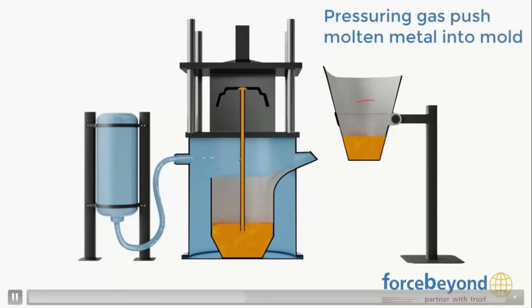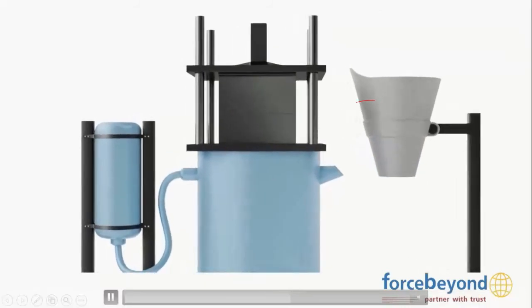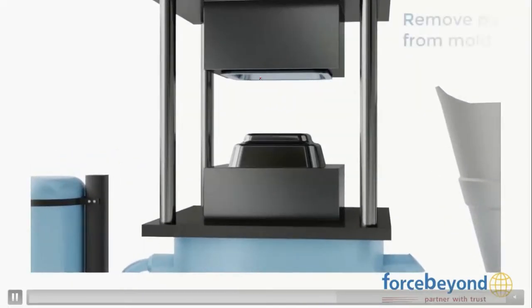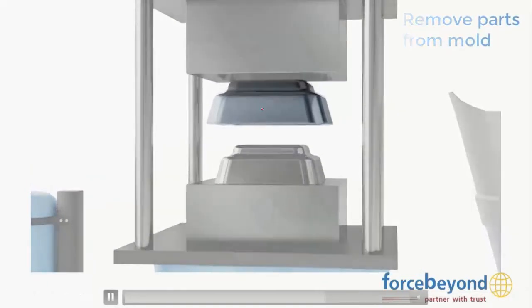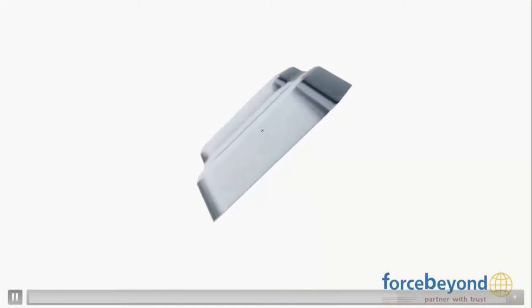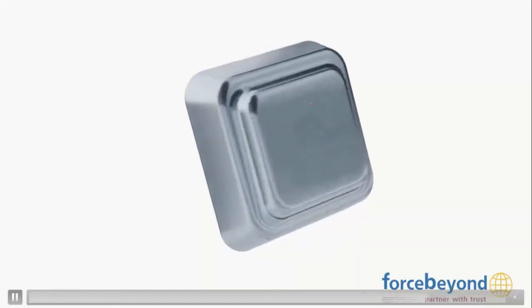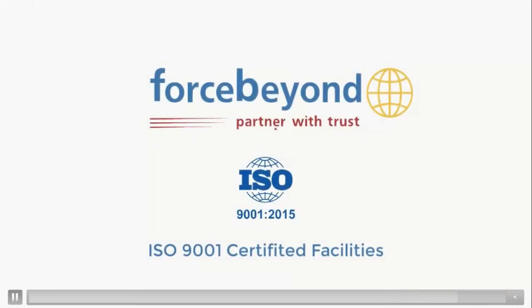Now we are supplying the air pressure, which pressurizes the molten material from the top so that it moves up into the mold cavity. So this is how we will get the product. We can remove the part once we open the die. So the resultant product is purer with fewer defects and less porosity, and hence it has higher mechanical properties.